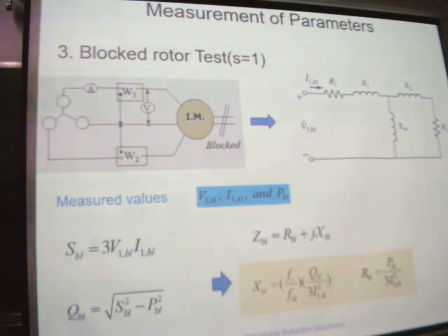Block test. The rotor is not allowed to rotate, and we just lock it using a mechanical method. Don't allow it to rotate. We give a voltage here.